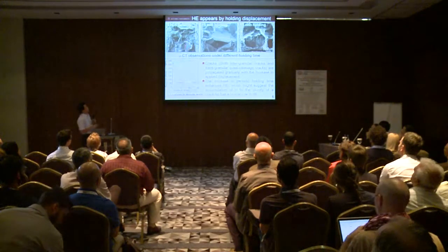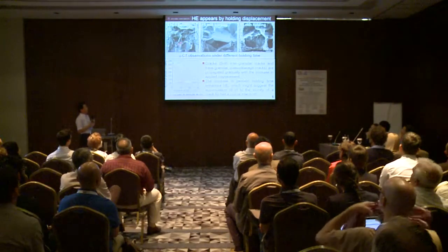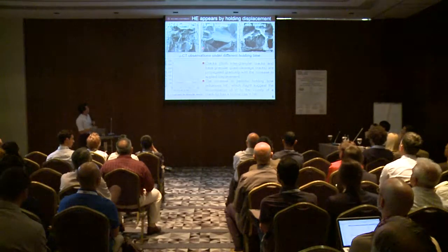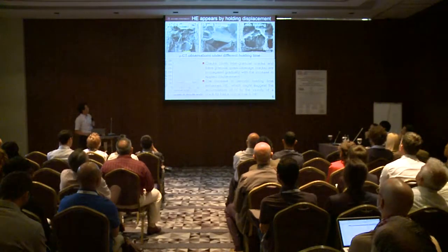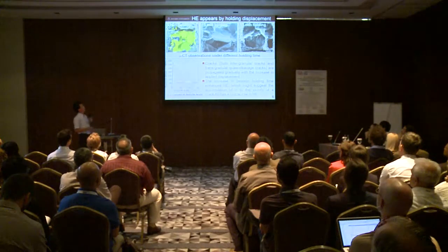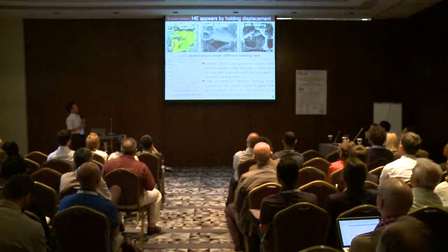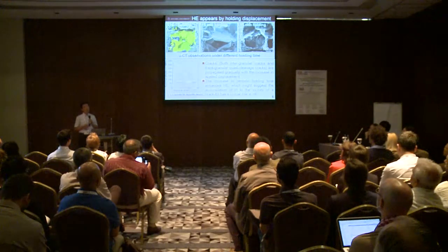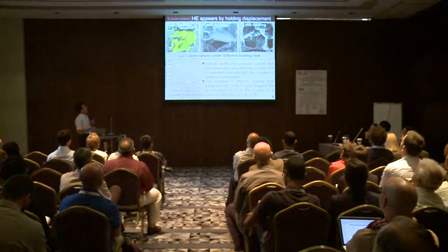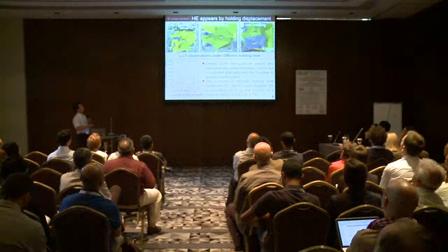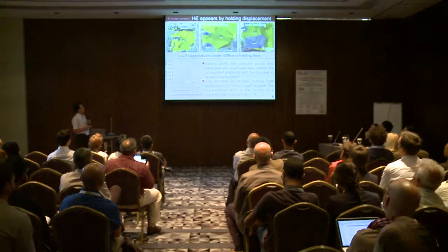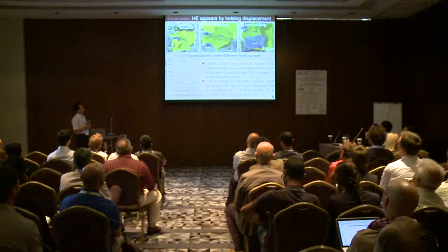We are now superposing a series of 3D crack images onto this SEM micrograph. This is the initial crack. Actually, it is a quasi-cleavage crack. It then propagates fairly gradually with loading. In this case, about 30% of the fracture surface was covered by intergranular cracking and quasi-cleavage cracking. If you increase the holding time from 5 to 45 minutes, almost the entire fracture surface is covered by hydrogen embrittlement. Then strength and ductility decrease drastically.